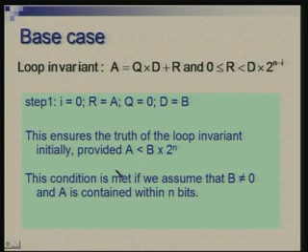Although in the illustration which I took, I had taken 8 bits for the dividend, with the intuition that when you multiply 2 4-bit numbers, you will get an 8-bit product. So, I started with an 8-bit dividend and tried dividing it with a 4-bit divisor, but there are cases where this may not work. Okay.